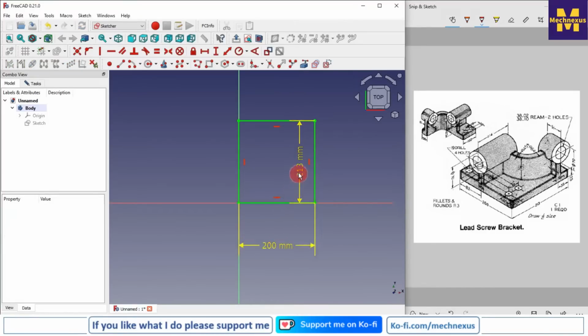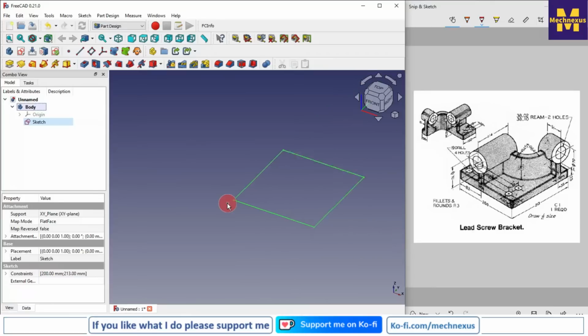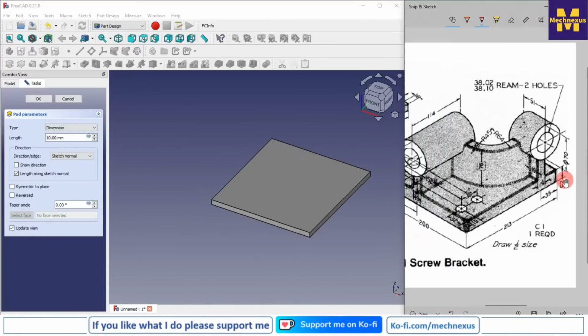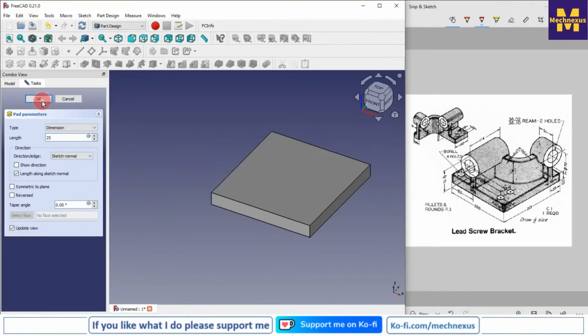Now I move my dimensions, and I will come out of the sketch, and I select my sketch, click on the pad, and this thickness, if we zoom it, we can see that it is 25 mm. I will give the 25 mm value and I will say OK.